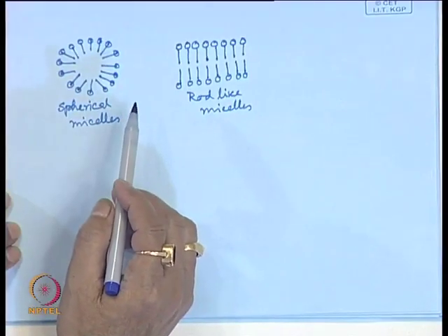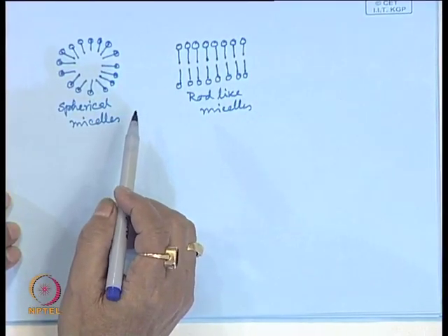Now, we are going to study this emulsion polymerization system. Here also, what do we do? We add monomer in water. Water is the dispersion medium. In that dispersion medium, we put monomer, that is organic in nature. In order to stabilize the monomer droplets formed by mechanical agitation, we add soap molecules.